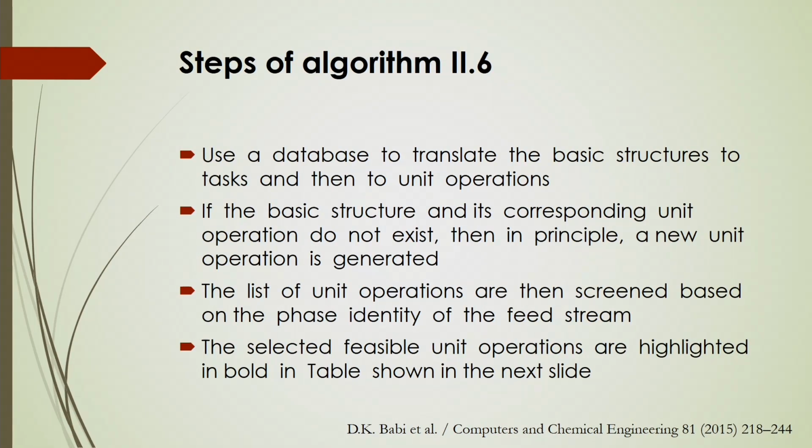Now, what are the steps of algorithm 2-6 there? In this case, you have to use some database to translate that basic structure to tasks and then to unit operations. And if the basic structure and its corresponding unit operations do not exist, then you have to generate a new unit operation. After that, a list of unit operations is screened, and you identify the feed stream based on the phase identity. And also the selected feasible unit operations are then highlighted in bold in the table, as shown in the next slides.